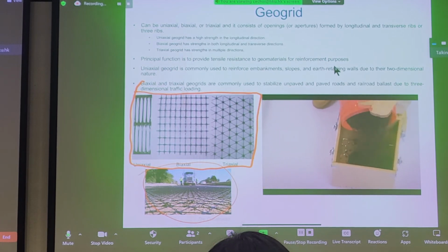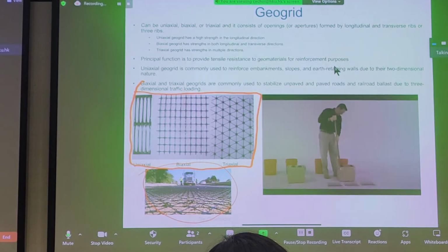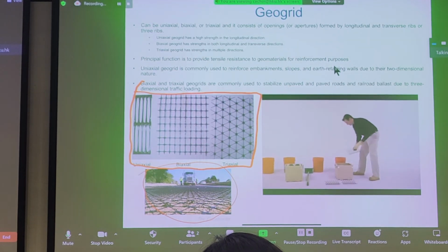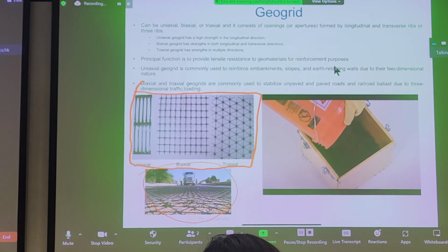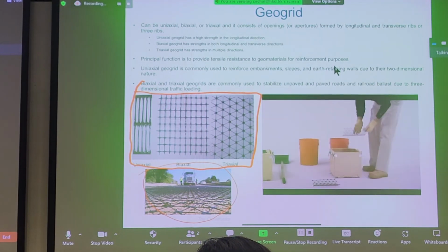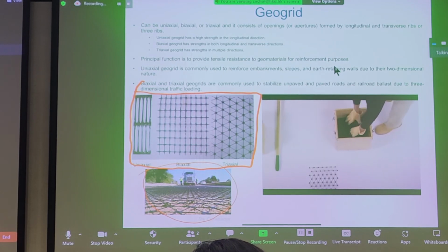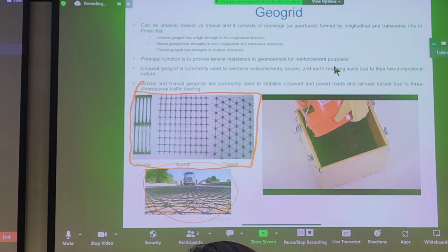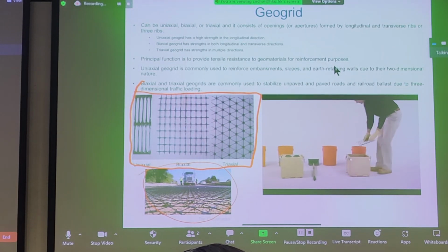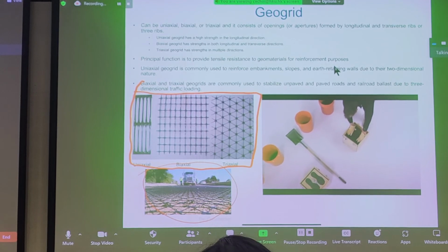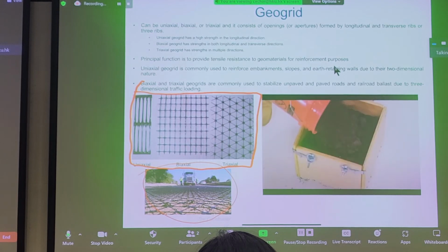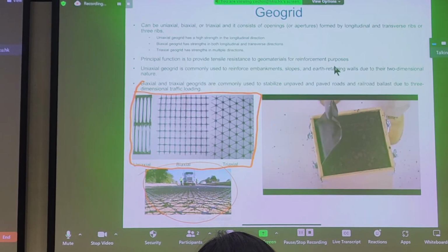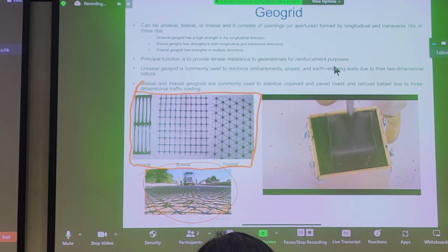And then the second one is he's going to build it like a mechanically reinforced wall. Lift of soil, place geogrid, another lift of soil, another layer of geogrid, until he gets to the top. Then he's going to show the substantial improvement in shear resistance due to added tensile resistance from the geogrid.